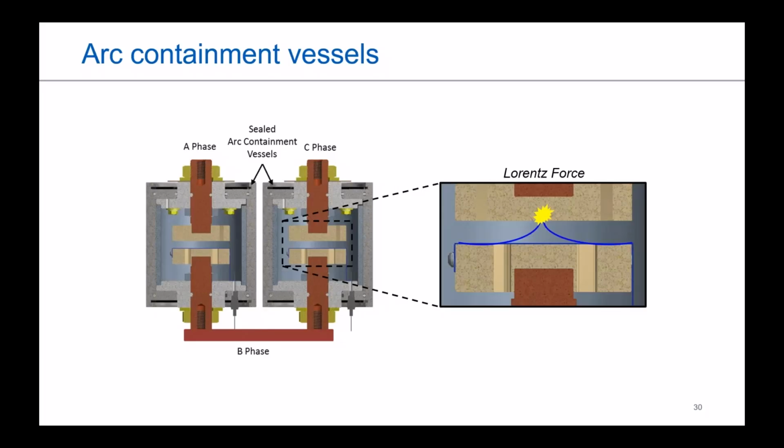Because of the phase angle difference between the 2 contacts, there's going to be a Lorentz force generated across that wire, which is getting the discharge on it, allowing it to then create a short between the 2 phases. And that's where the arcing gets maintained between those 2 contacts until the low voltage power circuit breaker can de-energize.